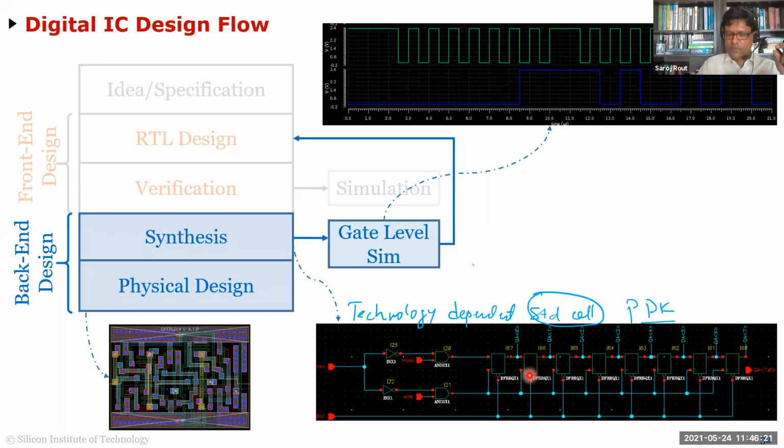In full custom design, there is no RTL. Same thing with the layout. When you're doing physical design, you do the complete layout by hand. You're not using any tool to automate the process. You might use the standard cells, which are already designed by the foundry house, but all the rest of the placement, chip planning, and routing, and if you have clock trees, everything is done manually. So that's what's called full custom. I think you're asking about both gate level and physical level. Can you raise your hand so I can ask you exactly what you're asking?